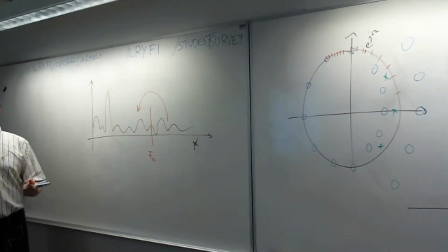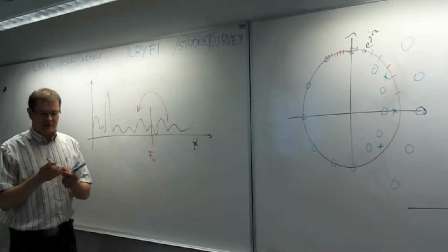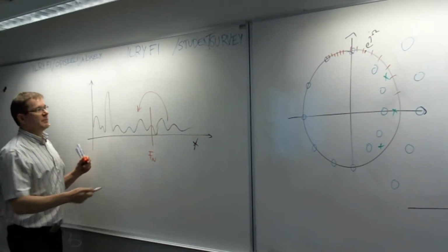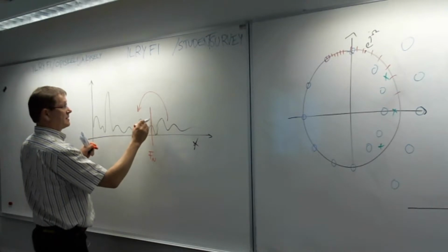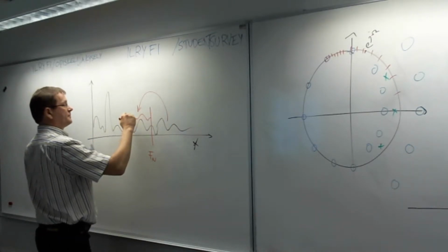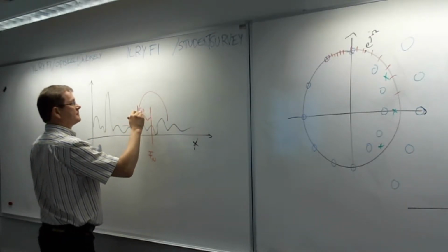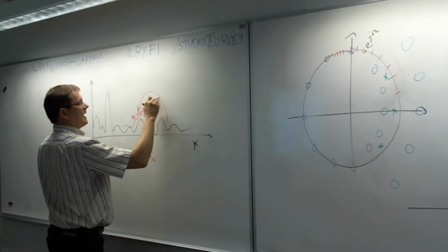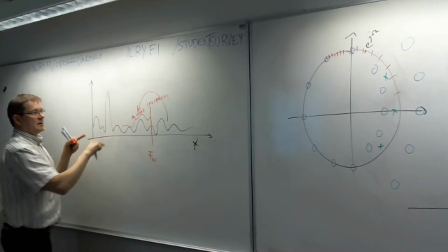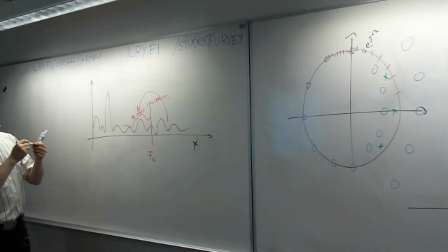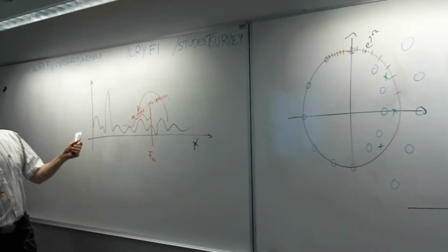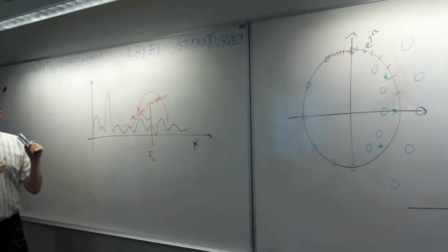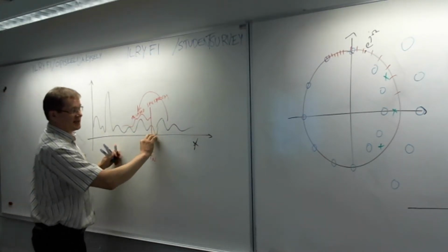We make the same aliasing error as we did in the very first lecture. So this one aliases here, and you get the aliased spectrum at the top of this one. If we have a fast enough sampling rate compared to the possible signal changes, this is negligible.